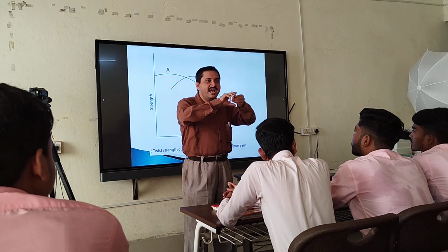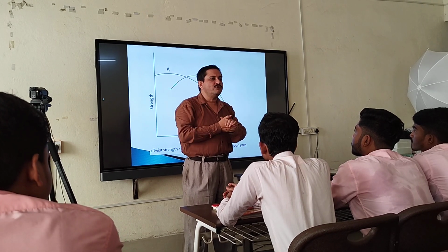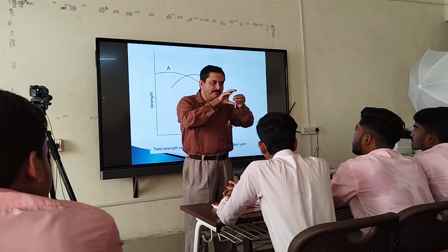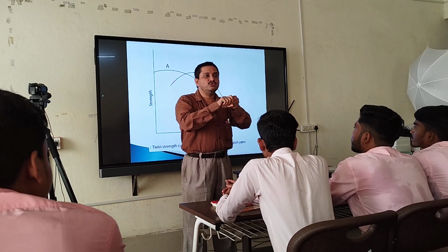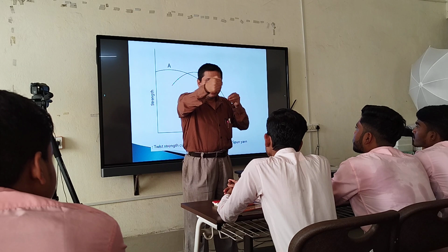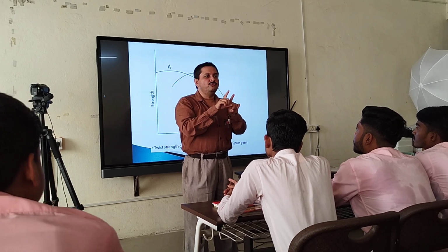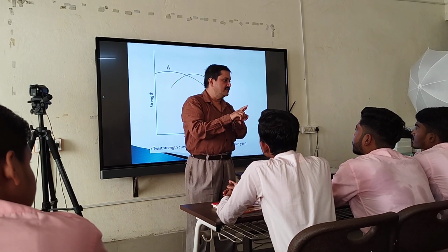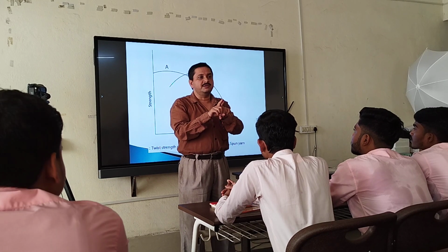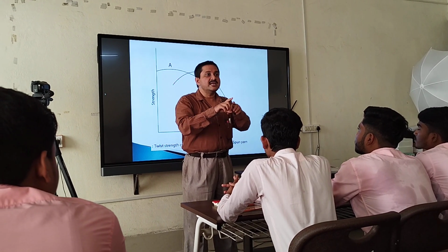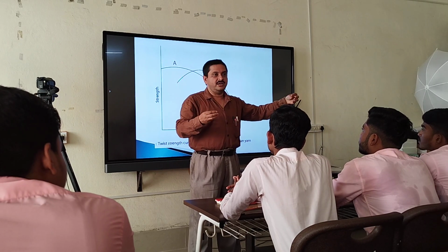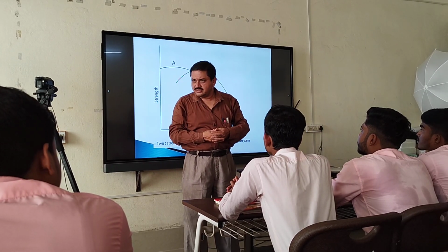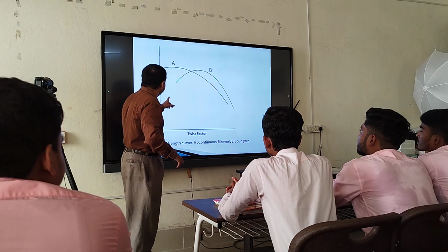Due to the compressive force, fiber to fiber friction will increase. Increase of fiber to fiber friction causes an increase in the load bearing capacity of the fiber strand. It means an increase of the strength. That is what we are observing.